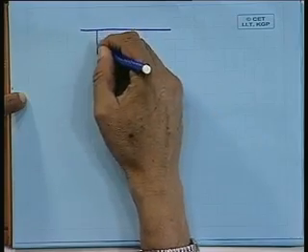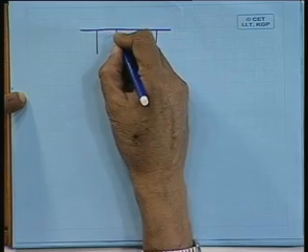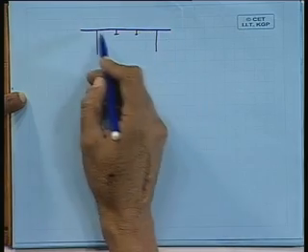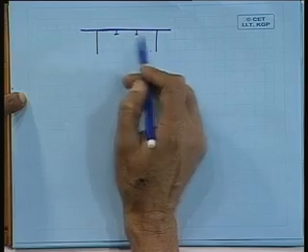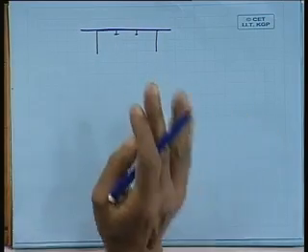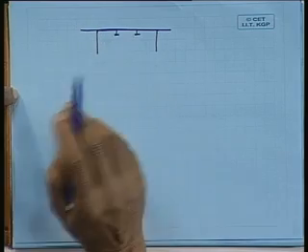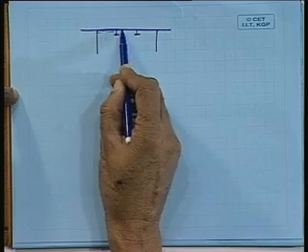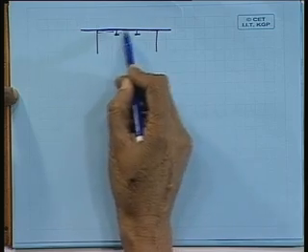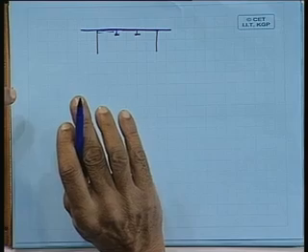You can say the bulkhead bending, you can even say that the top deck bending, you have the hatch end beams, you have one bulkhead here, another bulkhead here. So, if I say this is the bulkhead, this is the deck, you have one hatch end beam here, another hatch end beam here, and you want to find out how this particular hatch side girder is behaving. So, we can take the hatch side girder to be supported on the bulkhead here and at the two hatch end beams here. So, it becomes a 3-span problem supported at intermediate supports here.